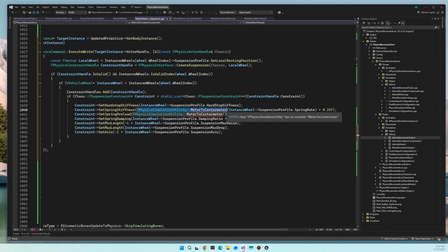Usually if you feel like you've got a large number, it's usually scaling. Unreal Engine works in centimeters. So here what we're going to take is I have a small number. We're going to multiply that to convert it from meters to centimeters, so that Unreal Engine can then process that. So sometimes you might just want to then put a conversion in there to take that large number and make it look a little bit more manageable. So let's go ahead and do that to finish this up.